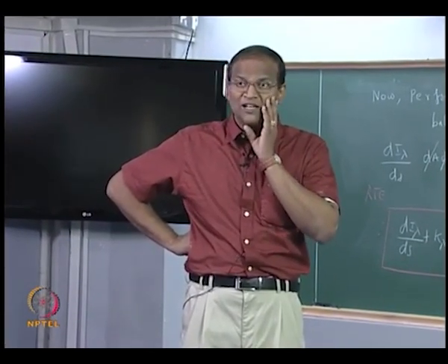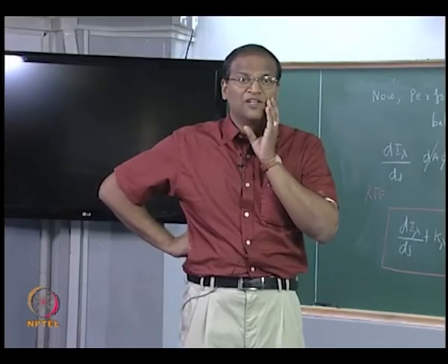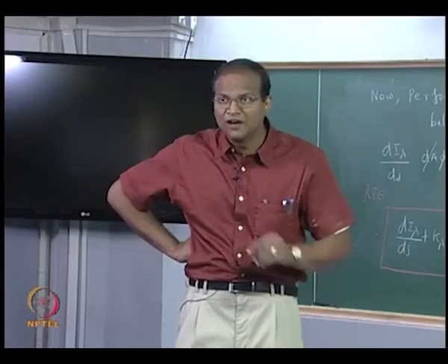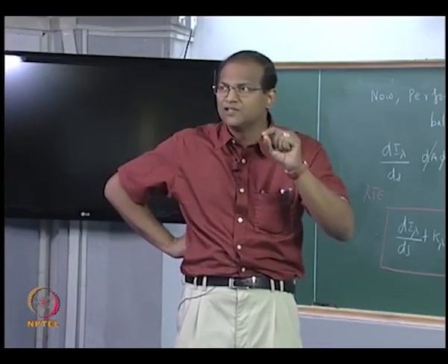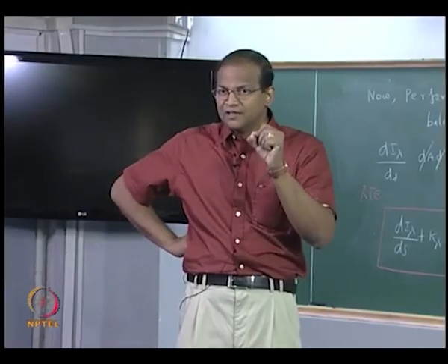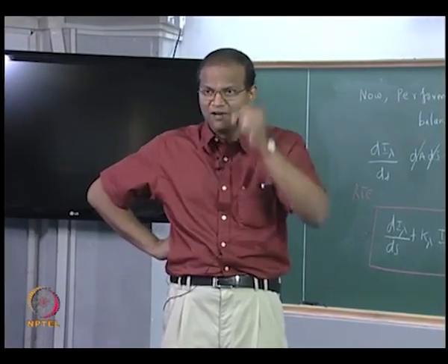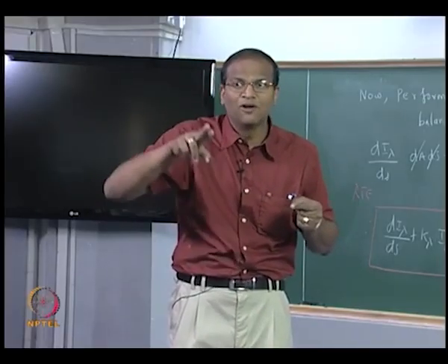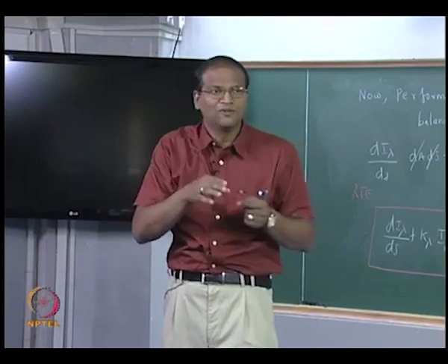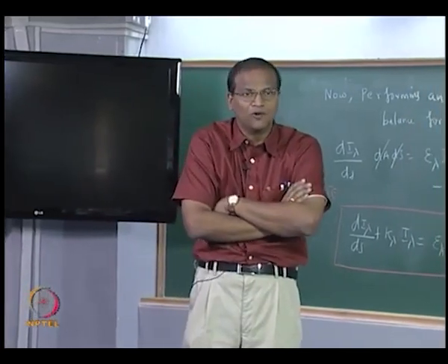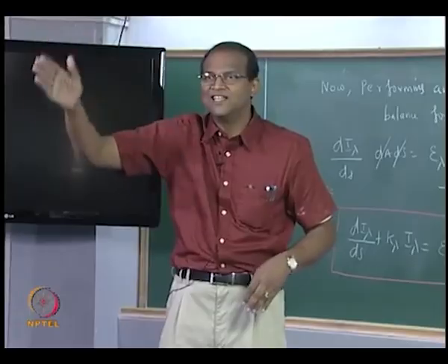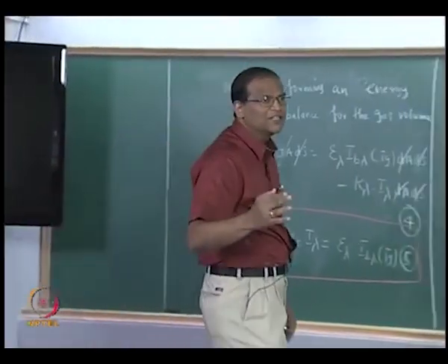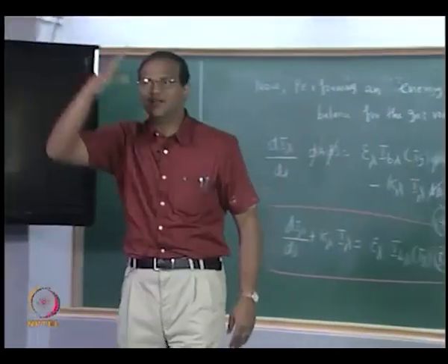Suppose we consider a 3 surface enclosure in which the temperature of each of the surfaces is varying with respect to x, and I cannot use the uniform radiosity assumption. Then I have to divide each surface into subparts, and J1 itself will have several parts. Therefore, instead of summation I have to use an integral. The radiosity equation which I told you, where J equals epsilon sigma T to the power 4 plus 1 minus epsilon sigma F_ij J_j, will become an integral. So the radiosity equations by themselves are integral equations.